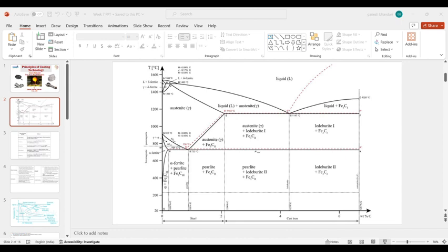In diffusion annealing, hypoeutectoid, eutectoid and hypereutectoid steels are heated uniformly and the component is held at a temperature between 1000 to 1200 degrees Celsius and then cooled very slowly in the furnace in order to remove the heterogeneity in the compositions of heavy castings. So we are trying to homogenize the phase structure of our sample. We can term it as a homogenization process also.